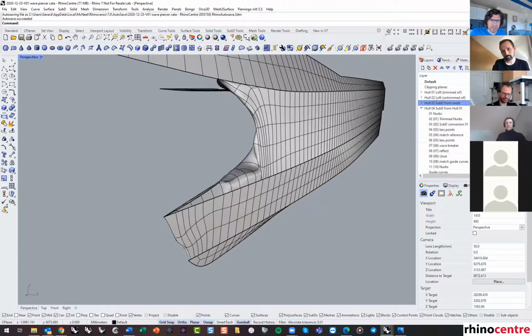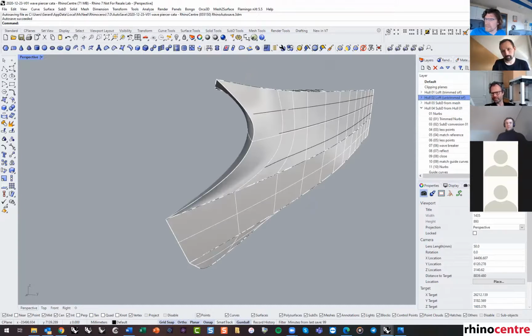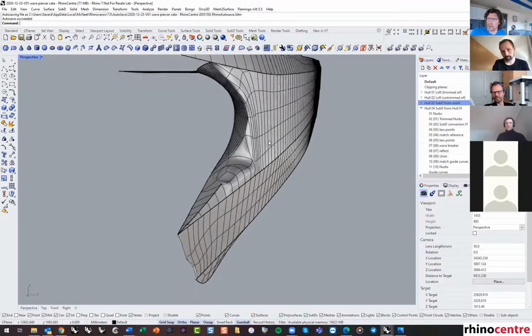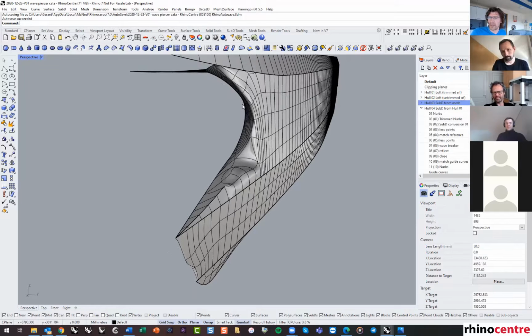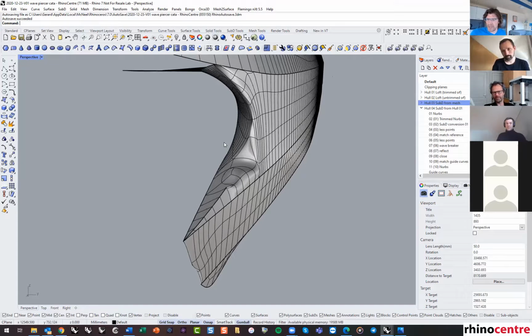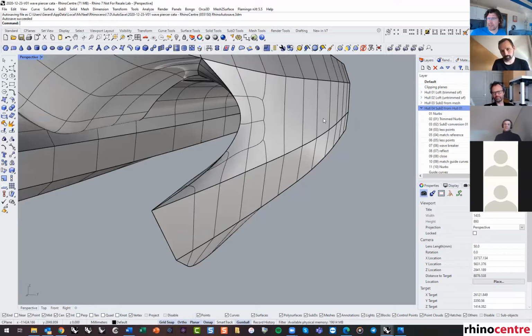So you didn't use Loft and then create a subdivision of that? Yeah. Oh, you did in the end? First I modeled something from Nurbs surfaces. Yeah, but it didn't work. A rough one, and then I converted. So you can convert a Nurbs surface to a mesh, and then you can convert the mesh to the Nurbs. But it took me a while, and I haven't focused that much on the most clever technique. That would be the next step in my personal development in doing this specific job.